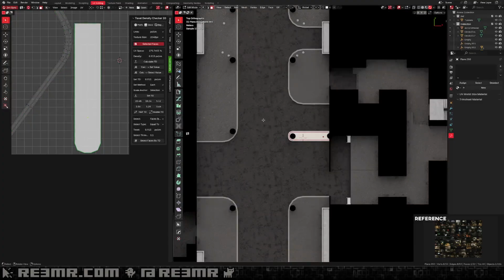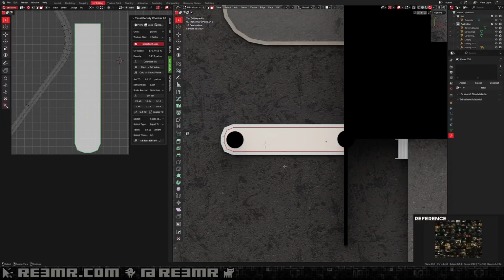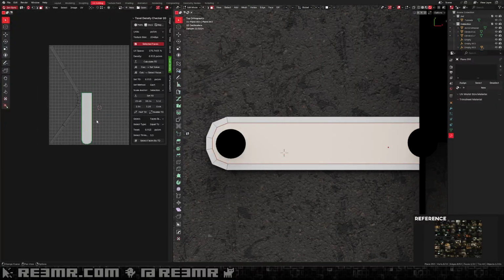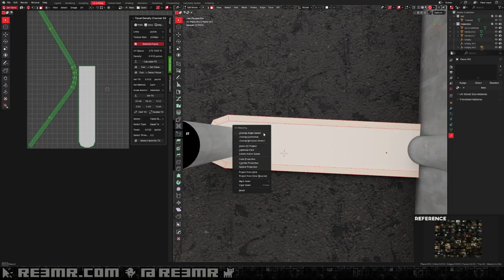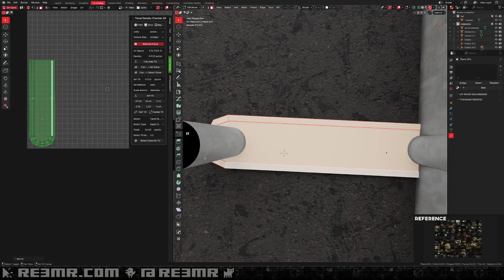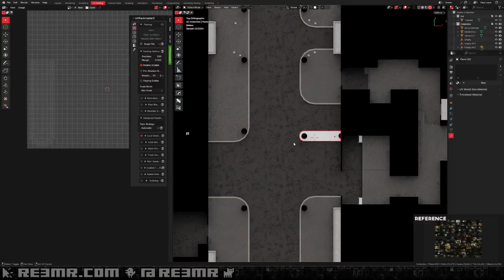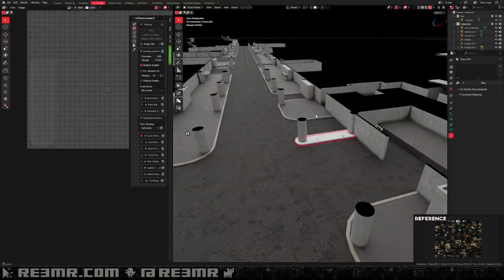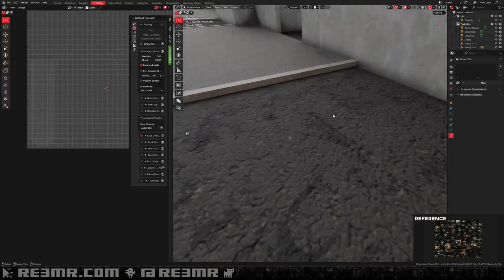And then I think I forgot to set the texel density up here, but whatever, we'll do that last, I guess. Yeah. So now I select this island here, I pin it with P, then I remove the seam and unwrap again, which gives me that border back to the island. And then it's not really necessary, by the way, to do this. It's just in case I want to pack everything later in a nice way.